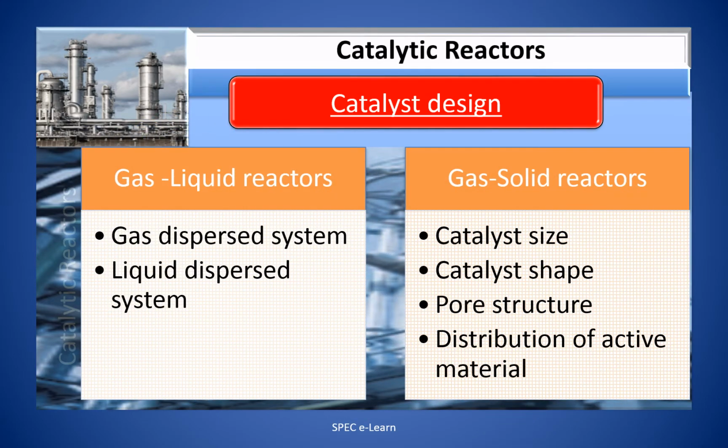First, catalyst design. Gas liquid reactors: you can have a gas dispersed system or liquid dispersed system. Gas solid reactors: the important approaches are catalyst size, catalyst shape, pore structure of the catalyst, the distribution of the active material in the catalyst.